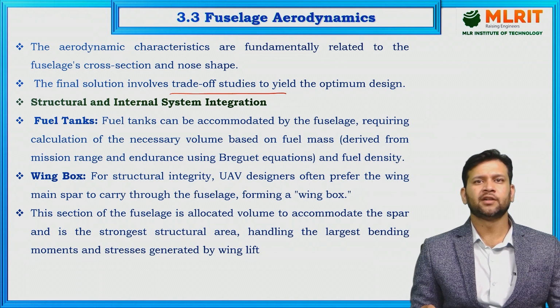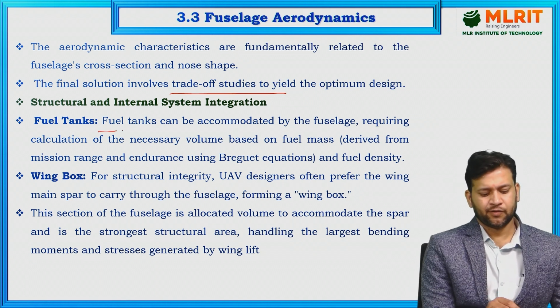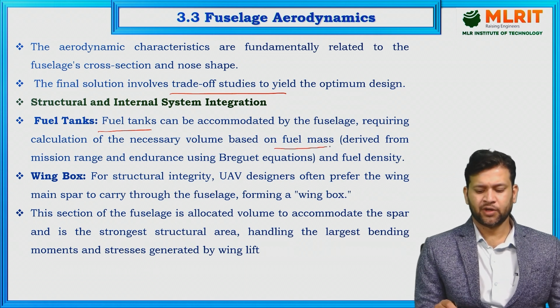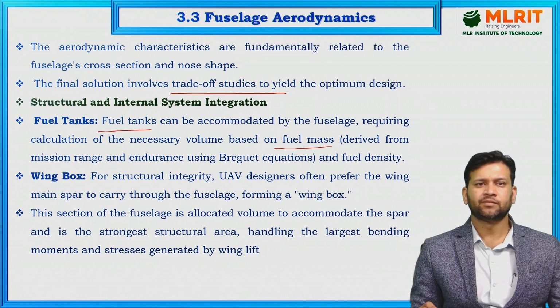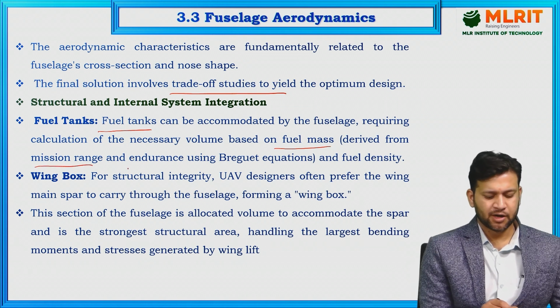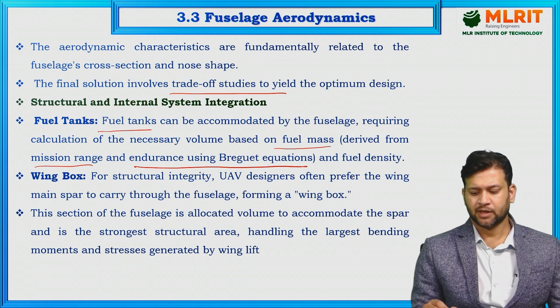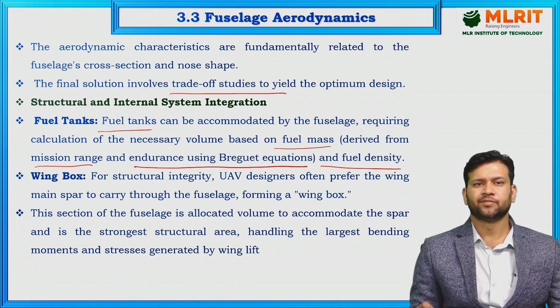Structural and internal system integration. Fuel tanks. Fuel tanks can be accommodated by the fuselage, requiring calculation of the necessary volume based on fuel mass derived from mission range and endurance using Breguet's equation, and fuel density.